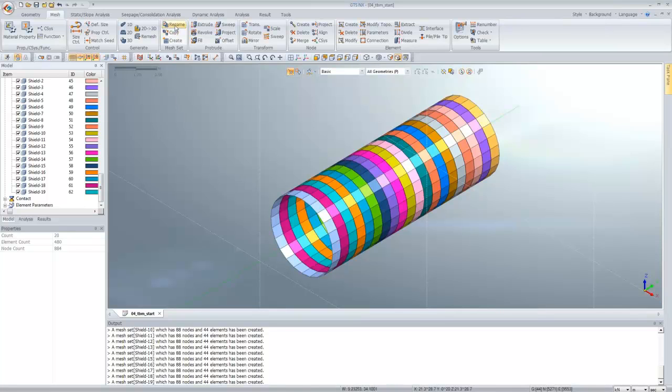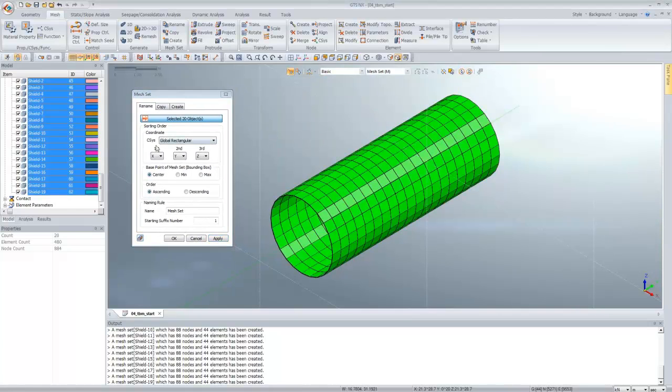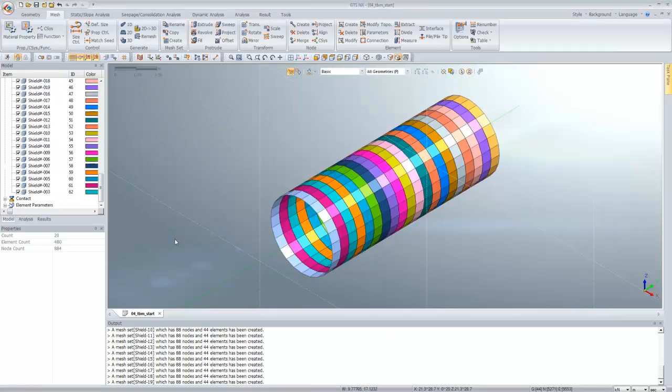So to assure that it's named correctly, just go to mesh sheet, rename. In the rename option, just select all, and you can change it to the y-axis for this direction, that is 1, 2, 3, 4. Mesh sheet name, so you should clearly define a standard mesh sheet name so that you can use the construction stage wizard available with MIDAS GTS NX. So seal 1 and just click OK. Now to check, you can just check.